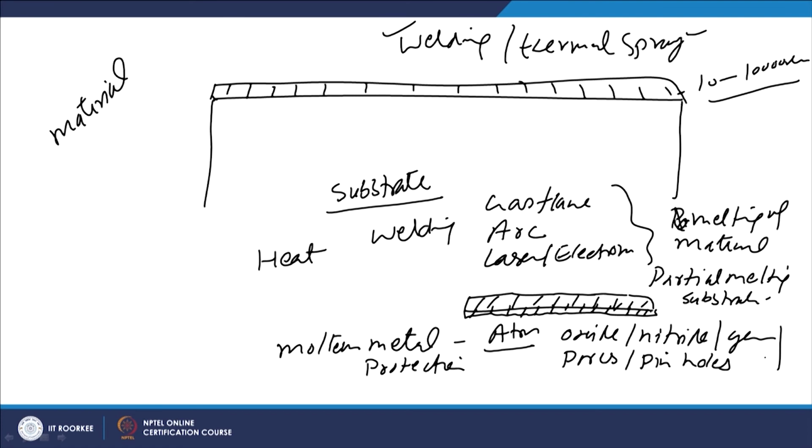There is another aspect. The metal which has been brought to the molten state, and the intermixed layer in the molten state, will solidify. Solidification of the molten layer is another aspect that will govern the kind of properties the modified surface layer achieves, which in turn affects its mechanical as well as tribological properties.